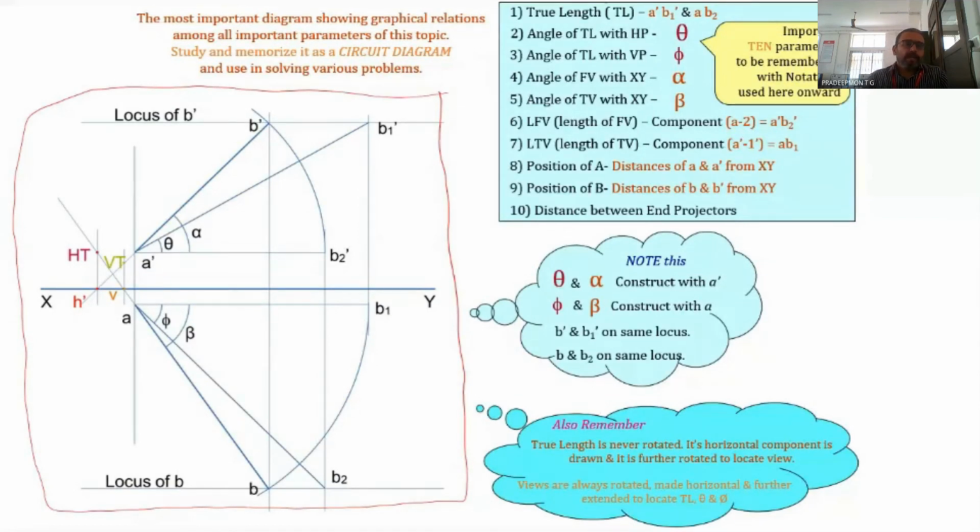First you fix A dash and A, then draw AB as well as A dash B dash. B dash and B should be in the same vertical line. Then you draw AB2, and you find out B2 dash. A dash B2 dash should be of equal length as A dash B dash. Just a freehand drawing is enough. Then you find out A dash B1 dash. We locate B1 dash, then AB1 is of the length equal to AB. So this freehand drawing is fully necessary.